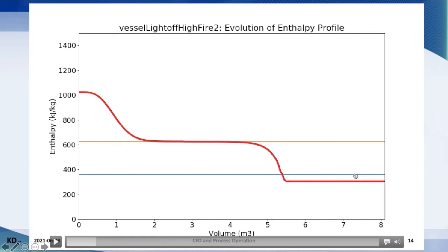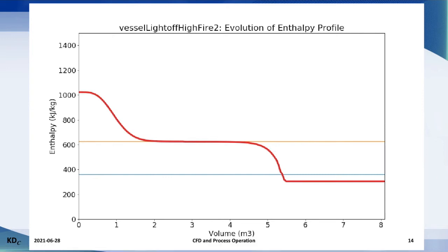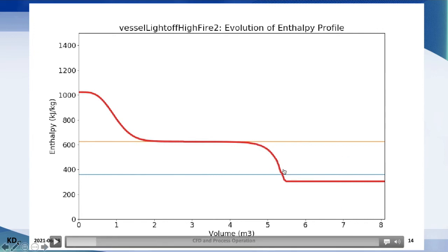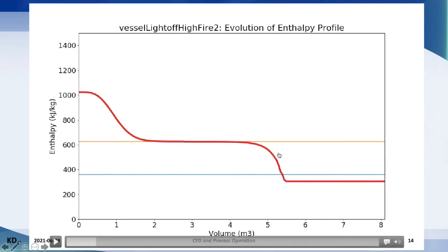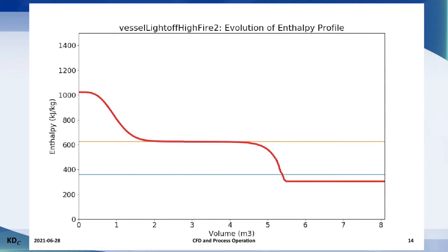Now, close behind this is the rapid increase in liquid enthalpy from 360 kilojoules per kilo to 630 kilojoules per kilo. And this is where the bed becomes more filled with vapor. So this region here is where the bed is becoming de-inventoried. So this represents pushing this liquid piston of liquid hydrocarbon out of the bed. And over this region, the temperature is remaining constant.